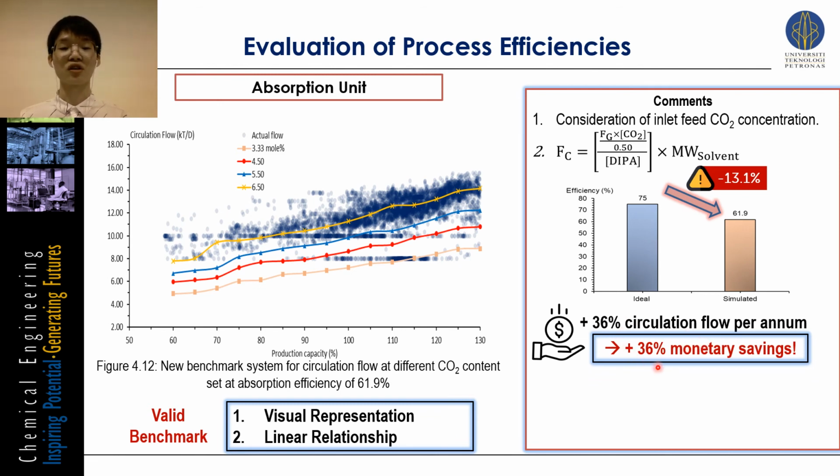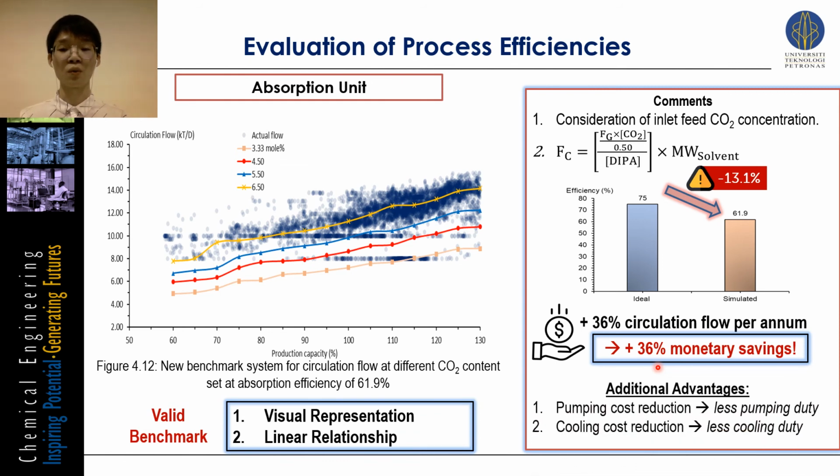And do you think that's the only advantage? My answer will be no, because there are additional advantages in terms of the pumping cost reduction, because there will be less pumping duty due to the less circulation flow requirement, and also the cooling cost reduction because you require to cool down less solvent and thus less cooling duty.